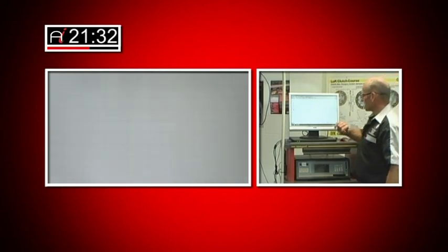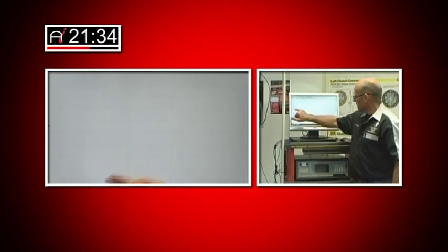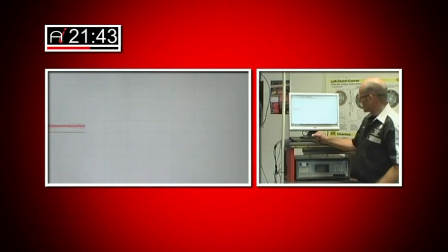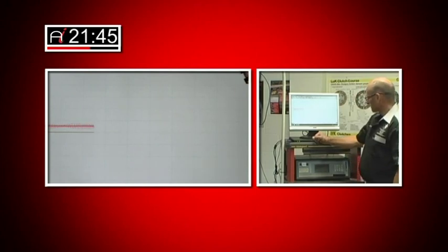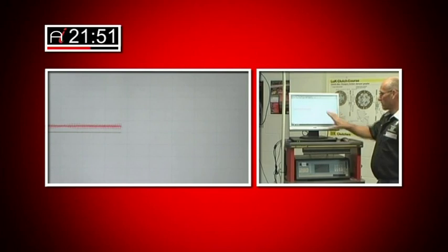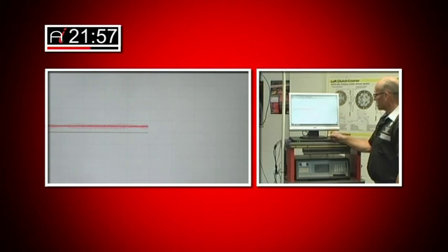So all we're interested in at the moment is looking at the voltage from the rail pressure sensor during this profile testing technique. So I'm just going to wait until it's passed across the screen. Unfortunately, when we use this screen, it denies me access to the keypad for stop and start. So we're just going to allow that to continue across the screen, and then we'll begin our test very shortly.